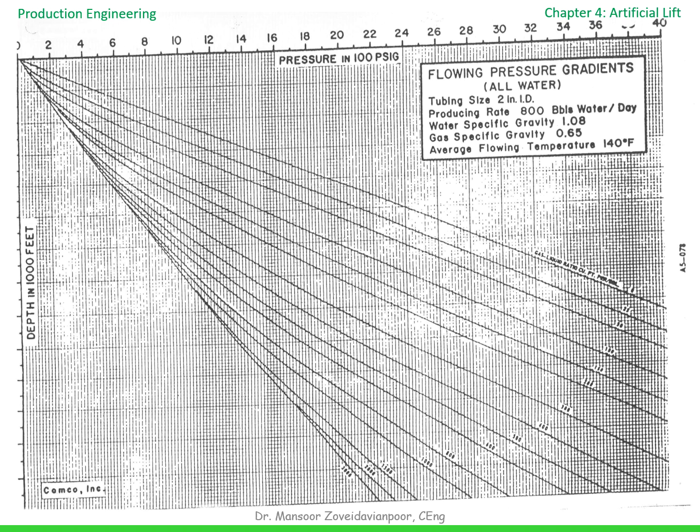This is a typical pressure distribution chart used throughout gas lift design. Each curve represents a different GLR condition. By selecting the correct curve and applying the chart depth correction, we can estimate tubing pressures at various depths. In practice, this chart is the source of the pressure data used to develop GFA and GFB.